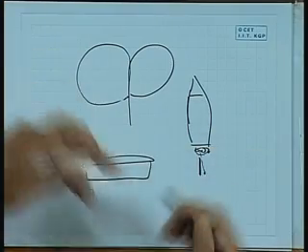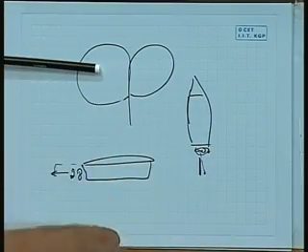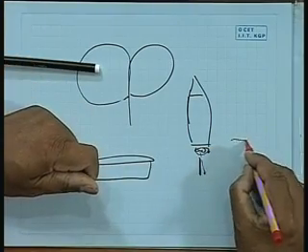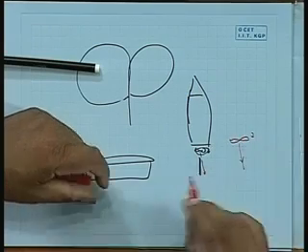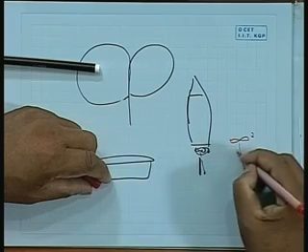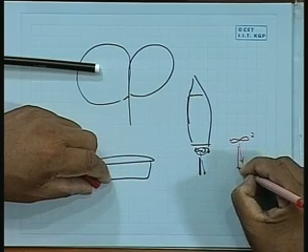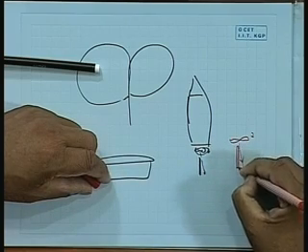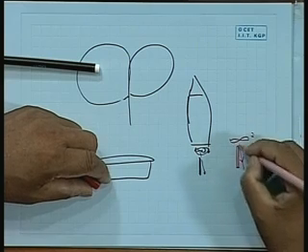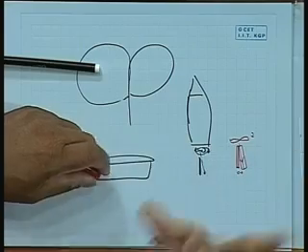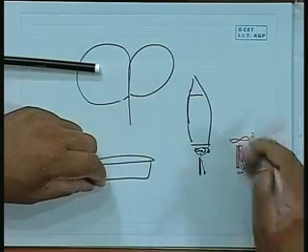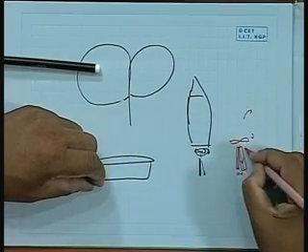What would happen is that because of this propeller, the thrust on the rudder, the propeller is moving in one direction. So the flow direction will be on average this side, not a straight line. Therefore, if the rudder is here, flow will be coming on this side, and in other words if you keep the rudder at this small angle, this will be the neutral angle. No turning force will come. Therefore, if you want to turn this side, I have to give more rudder here.